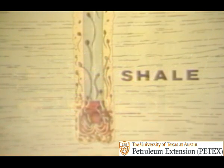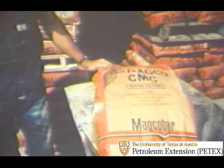All saltwater muds are inhibitive. The water phase has some chemical in it that retards the swelling of any clays and shales that may be drilled. To lower water loss, a cellulose like CMC or a starch is added to saltwater muds. Cellulose or starches are used because bentonite does not hydrate very much in salt water. When high salt concentrations are present, a polyanionic cellulose is particularly useful.